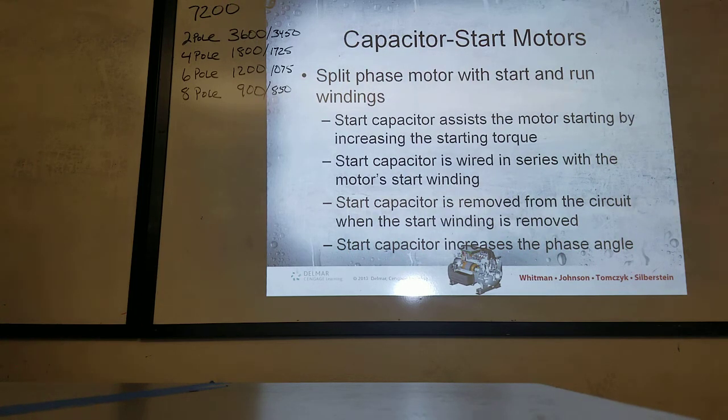So you didn't pay attention, that's all right. Well, that hole is called a blowhole. So that means that if that capacitor happens to stay in the circuit for any reason, like the contacts on the relay stick, it's going to blow out that hole and not blow the capacitor apart. Wow.